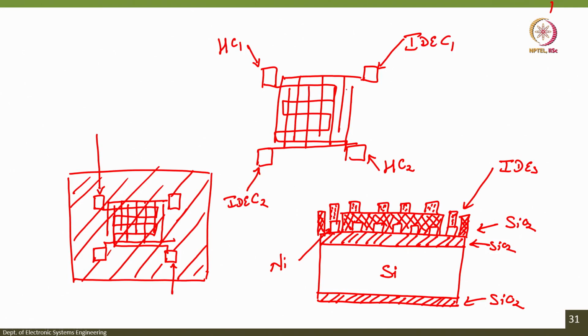So, between the interdigital electrodes and the heater, since both are metals, if I deposit metal directly over metal, I will have a short circuit, right. So, there should be an insulating material below it, and this is what we want to create. We also want to make sure that when we deposit the insulating material after the micro heater, the contact pads are opened, because otherwise you cannot take the contact from heater contact 1 and heater contact 2 if they are covered by the insulator.